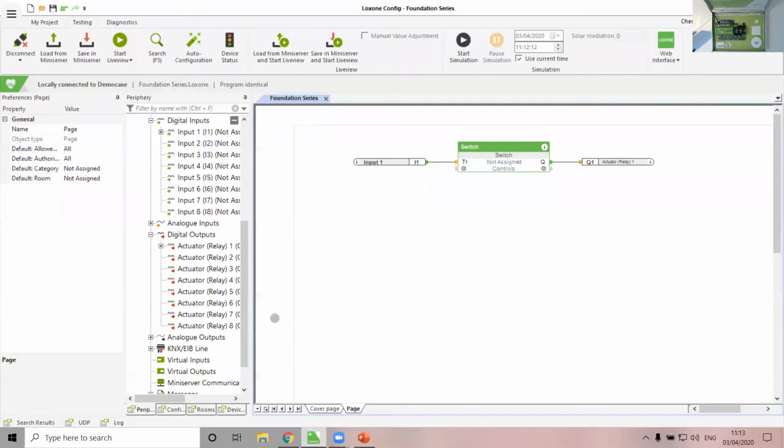But if you want to do what I've done and have the demo case connected to your local network so that you can be on the internet at the same time, then as you'll see here, I've got myself a network lead. I've plugged that into our router, and then I've readdressed the mini server. So I've plugged into the demo case. The mini server by default does something called DHCP, and what that means is it gets an address automatically from the network it's connected to.